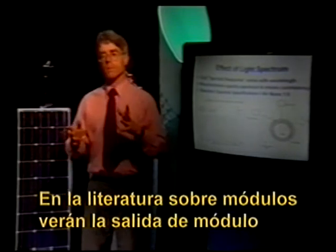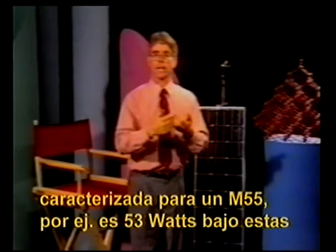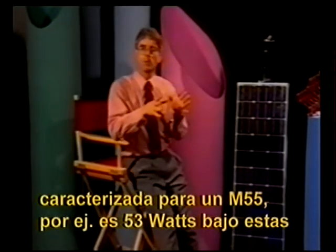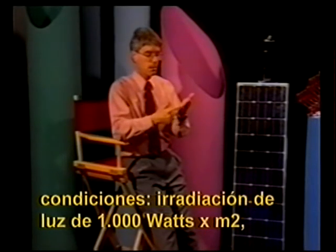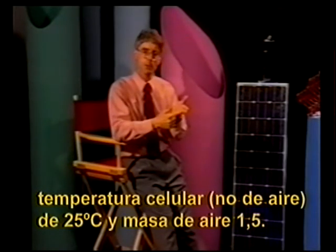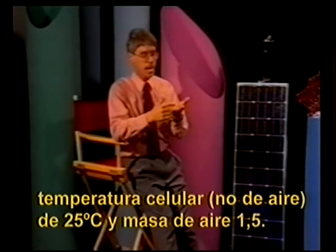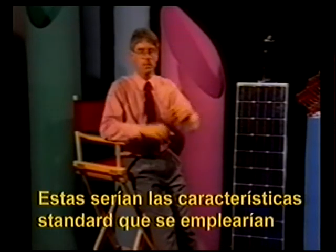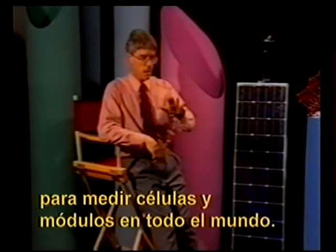So in literature that you read about modules, you'll often see module output characterized for an M55, let's say, is 53 watts under these conditions. Light irradiance of 1,000 watts per square meter, cell temperature, not air temperature, cell temperature of 25 degrees C, and air mass 1.5. These would be the standard characteristics that would be used to measure cells and modules around the world.